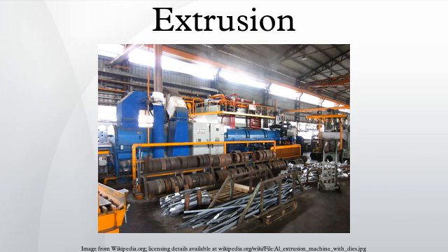Forming internal cavities. There are several methods for forming internal cavities in extrusions. One way is to use a hollow billet and then use a fixed or floating mandrel. A fixed mandrel, also known as a German type, means it is integrated into the dummy block and stem. A floating mandrel, also known as a French type, floats and slots in the dummy block and aligns itself in the die when extruding.